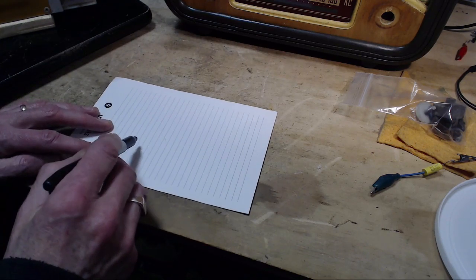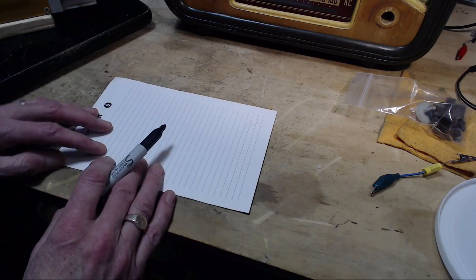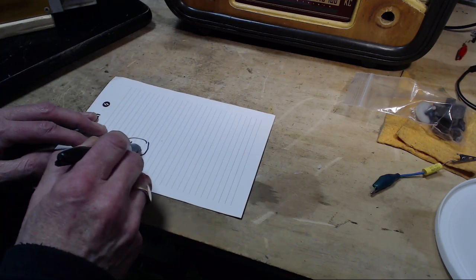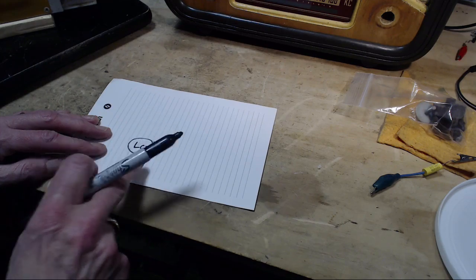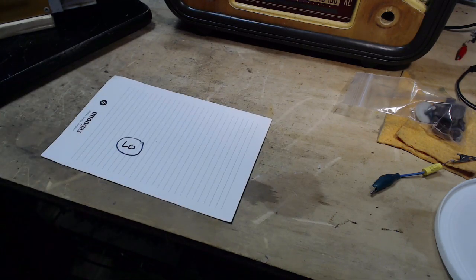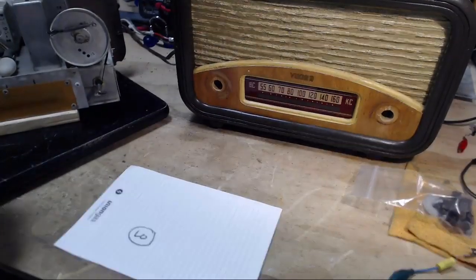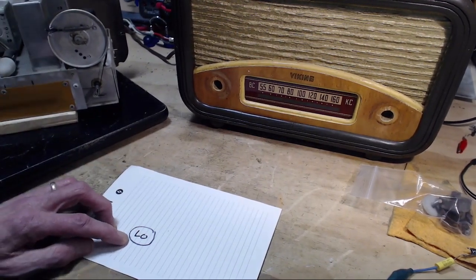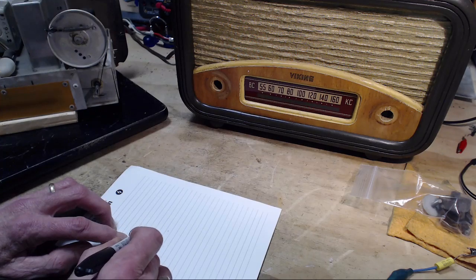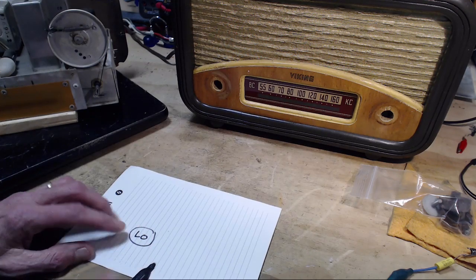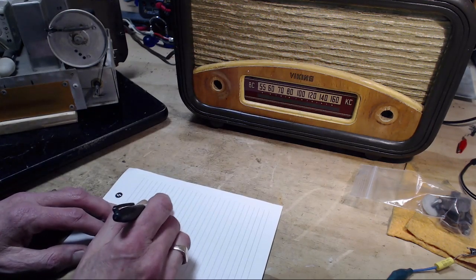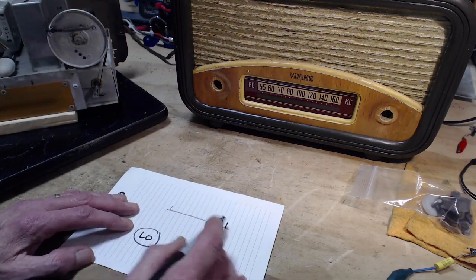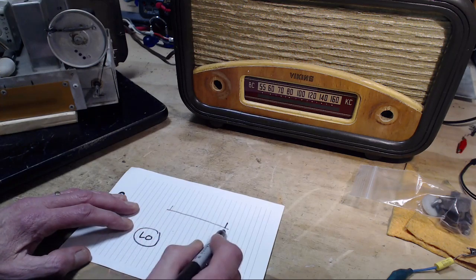So you have an internal oscillator in the radio. I'm just going to draw a circle here and call it LO, producing a frequency that's controlled by the tuning dial. So when you're turning this, one of the things you're doing in the radio is you're changing the frequency of the local oscillator. So we have the reception range, if you like, the range of frequencies the radio will receive. An AM band, this is about 500 to 1600.